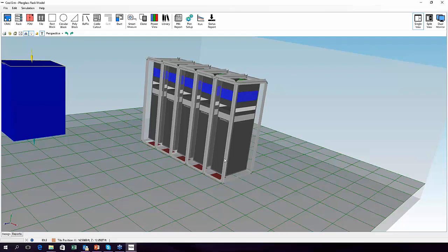We've found that in general these things do leak. Furthermore, it's very hard to make good measurements in a data center using instrumentation. Bolometers generally read off by 30% because as soon as you put a bolometer on top of a perforated tile, it affects the flow because the pressure is so low that it's difficult to capture it. So they tend to read off. They're off generally by 30%. They're generally underpredicting what's coming out of the floor. So I agree with you.